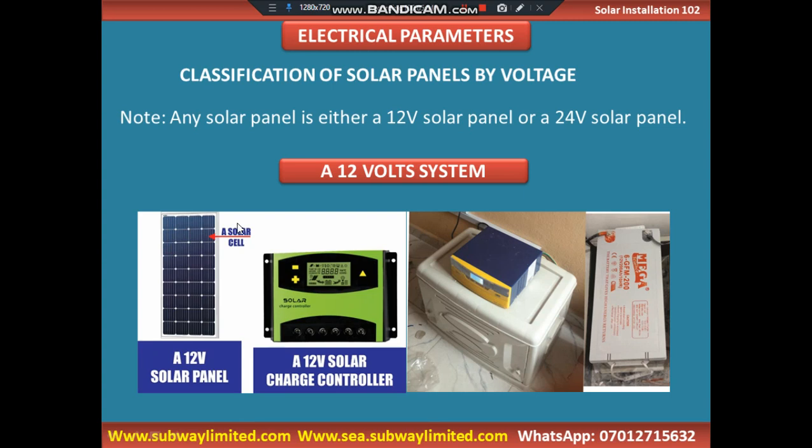So because we need to charge a 12 volt system, you certainly need a 12 volt solar panel to use for the purpose of charging this 12 volt battery, and to work with a 12 volt inverter, and equally to work with a 12 volt charge controller.